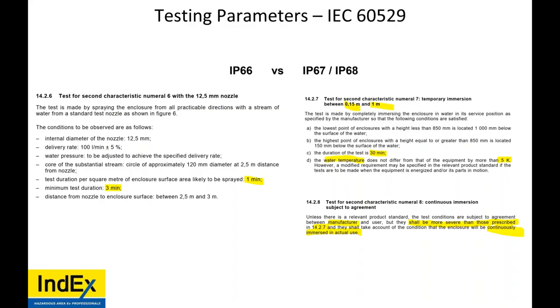Now, some equipment, let's say a gas detector, may have a deluge baffle which goes over it. When you change it, it says within the certificate and the data sheets that if you use this, it tells you the changed IP rating. But independent sunshades and rain hoods do not reduce the requirement of an IP rating. It's just an extra add-on that the specifications end user calls for, which protects their equipment from UV and lessens the chance of water ingress, because not all IP66 devices are going to survive perhaps 4 minutes of rain, 4 minutes of jets of water.